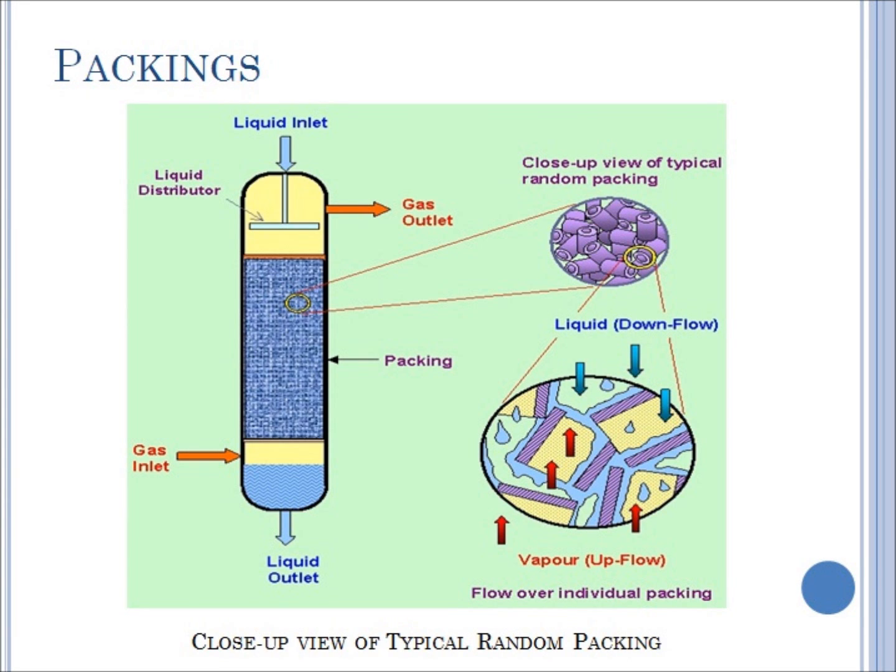Packings. Migration of unwanted components from gas phase to liquid phase happens in the packing, where a very intensive contact between both phases is organized. The performance of a packed tower can thus be improved by using the correct packing. In a well-structured packing, the contact surface between unwanted gaseous components and the fluid is maximized. This enables optimal efficiencies and thus low operational costs.